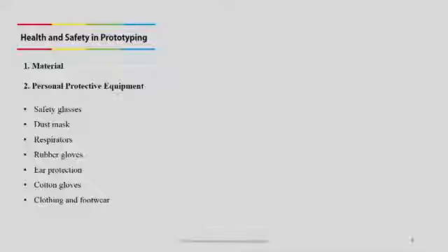And also, while working on the shop floor for prototyping, you should keep in mind what kind of clothing you should wear. You should not wear loose fitting clothes. You should also wear shoes while working on the shop floor.